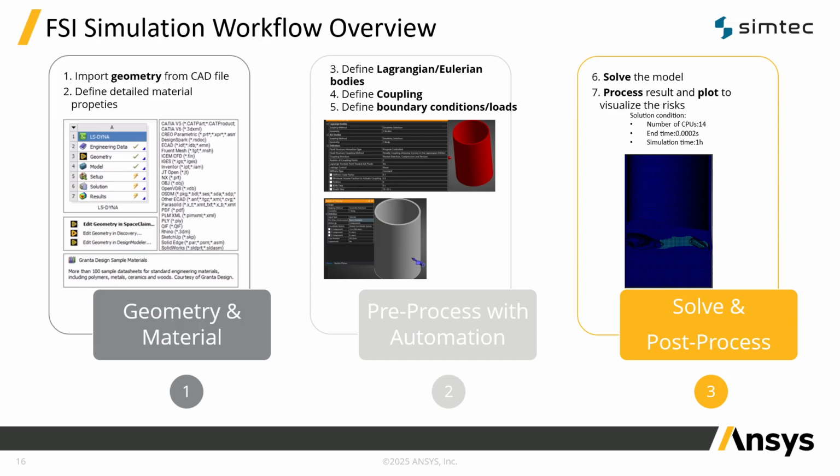Here we may be forced to define the following: pressure inlets, velocity boundaries, and so on, and structural supports and other kinds of constraints. After that, we should define the mesh motion and remeshing, which is a crucial part of this kind of simulation to achieving the best results possible.